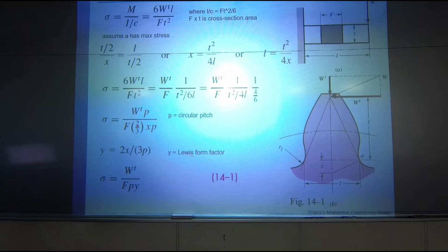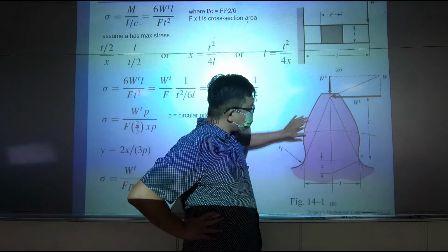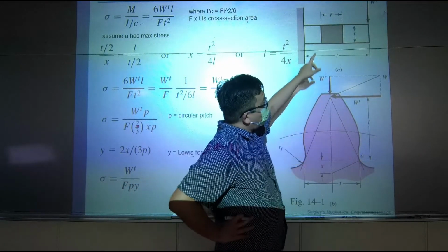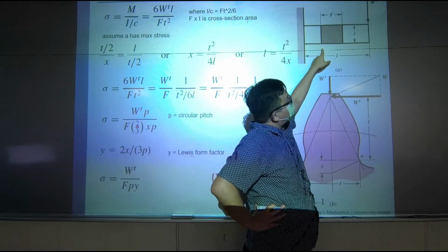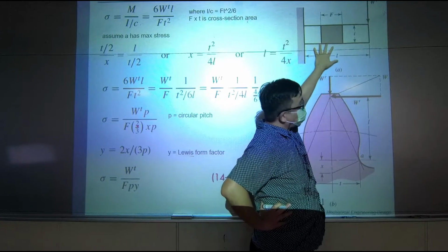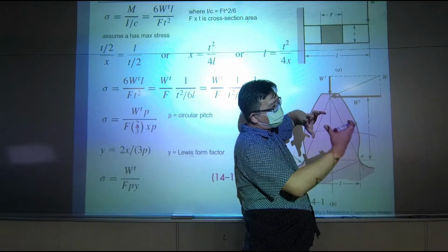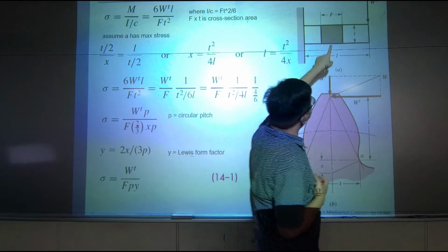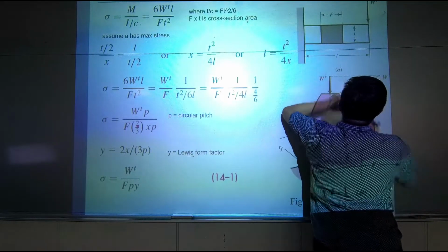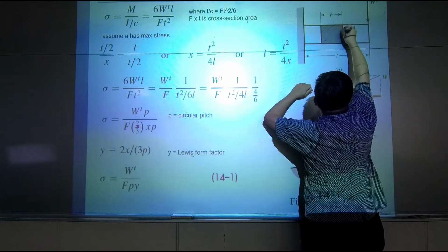After his development, after we have the equations like this, we can estimate whether this tooth can carry the load. So what he did was, he considered this shape as a rectangle. Okay, he simplified this as a rectangular cantilever beam.